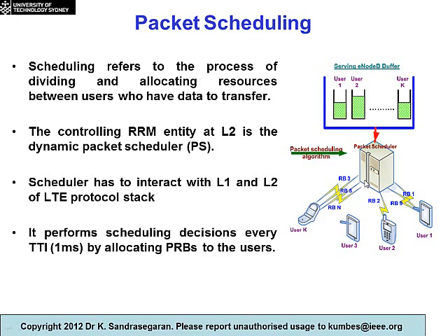And how do we transmit them? We allocate different resource blocks to different UEs. So whatever packet is in a UE's buffer is then transmitted on a specific resource block. Now, in order to make that decision, we need a packet scheduling algorithm in the E node B that decides how to allocate resource blocks to different UE packets. Okay, so just in summary, scheduling refers to the process of allocating resources for UEs to transfer their packets which are sitting in the serving E node B buffer.